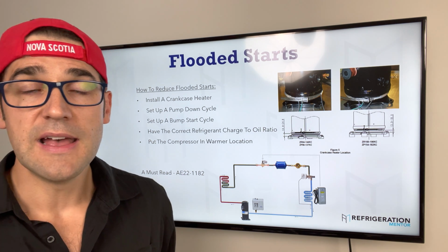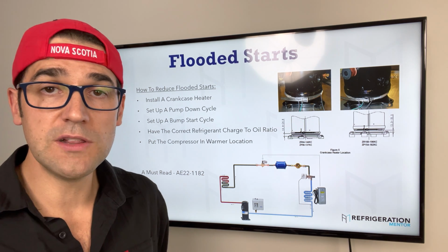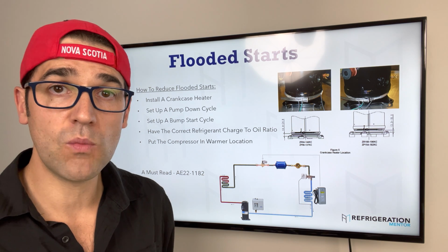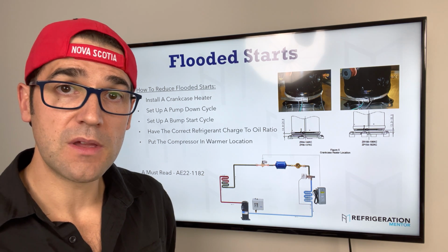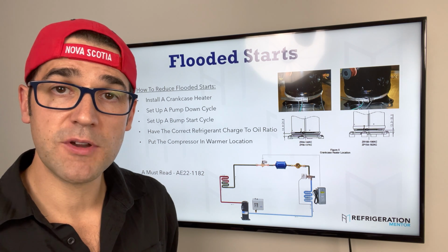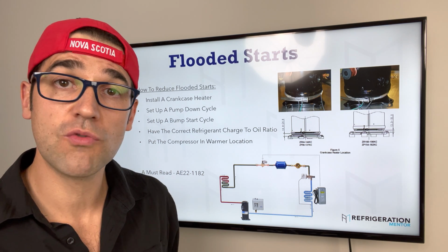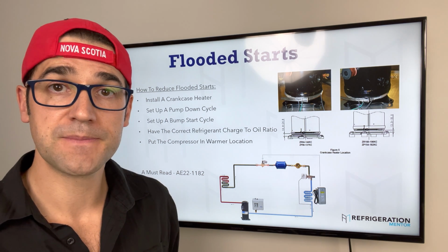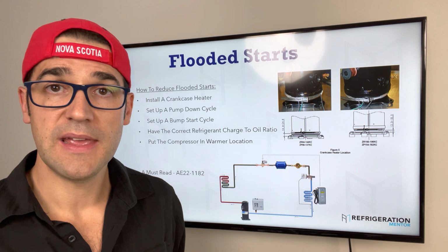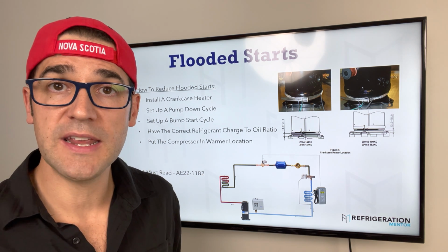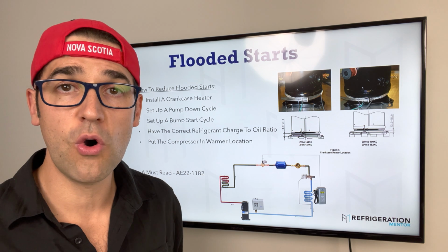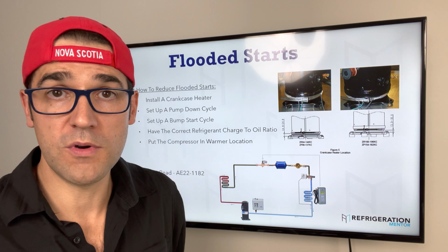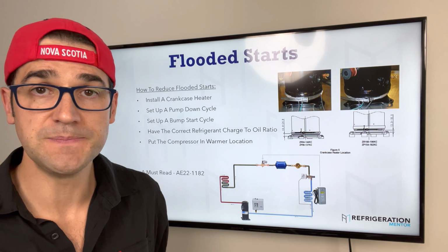Check out those guides. Another thing is maybe you need to relocate that compressor to a warmer ambient or a warmer location. I've seen it where people have the crankcase heater immersion in the semi-hermetic, plus they have a blanket on it. I've seen it where scrolls have been wrapped all the way around with heat tape, to keep it from getting too cold, because they're in such cold locations. So it'll turn on, keep it warmer inside there, so that refrigerant doesn't go inside that compressor.